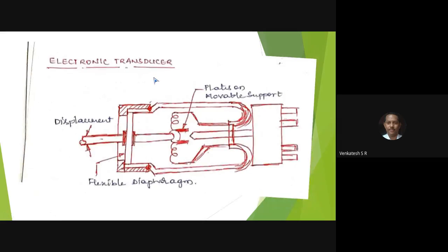All of you observe here, this is the instrument used for measurement of roughness of the surface plate made of cast iron or granite. All of you have seen the granite slab. That is used for conducting experiments on the granite slab in the metrology lab, and in the machine shop or workshop for marking of the workpieces. Marking is very, very important. For marking of workpieces, we have to keep the component on the surface plate so that you can easily mark the component.